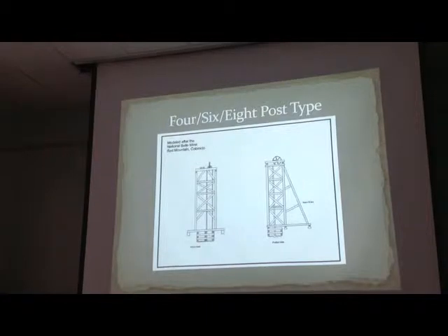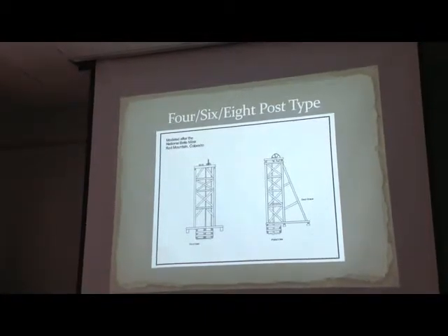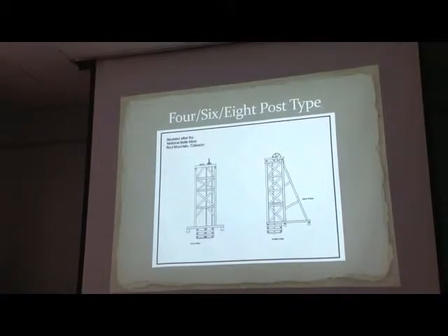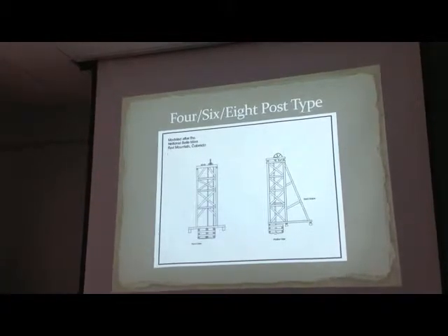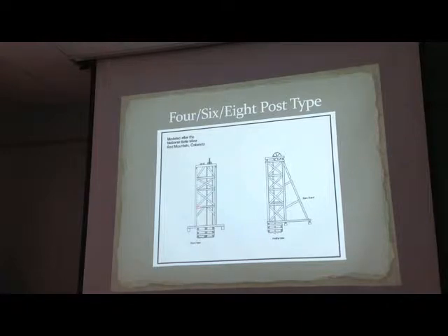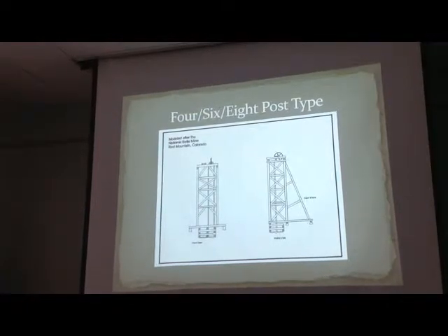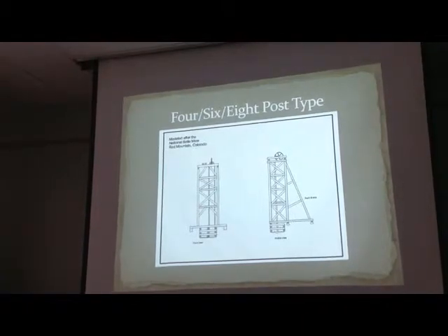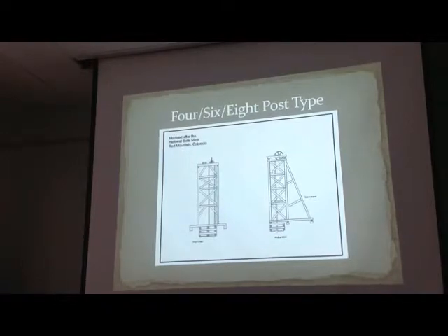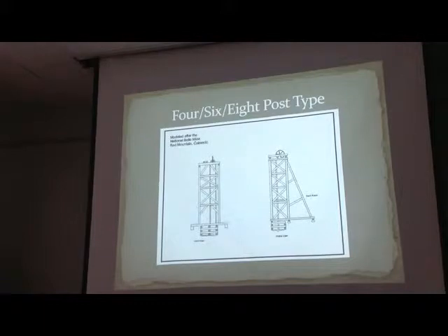Okay, 4, 6, and 8 post. 4-post head frames now, Mr. Twitty had them as separate types of head frames, but they're really, from an engineering standpoint, only the 4 outer posts and their bracing takes the wind pressure, so interior posts are redundant. These have a sill beam, foundation, usually fairly wide, and they can be of any height necessary.